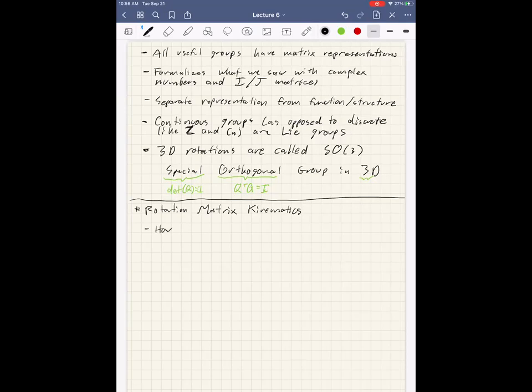To know what Q of t is at some future time. So how do I integrate omega of t from a gyro? Super practical question. I've got this thing coming from the gyro, and say I know Q naught. What I really need is to go from omega to Q dot of t so that I can integrate this up into Q of t at some later time. The mapping from Q dot to Q is obvious. That's just normal ODE stuff, but the mapping between omega and Q dot is what we're after here. That's a question mark.